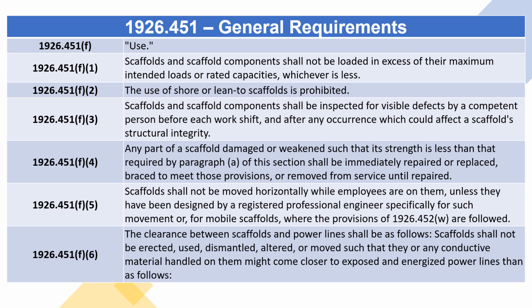1926.451(f)(5): Scaffolds shall not be moved horizontally while employees are on them, unless they have been designed by a registered professional engineer specifically for such movement or, for mobile scaffolds, where the provisions of 1926.452(w) are followed.